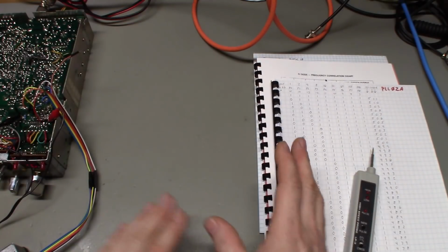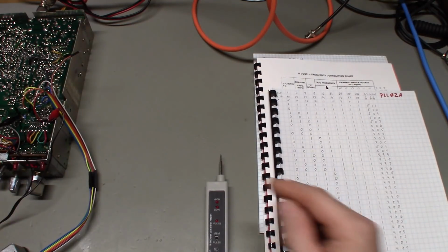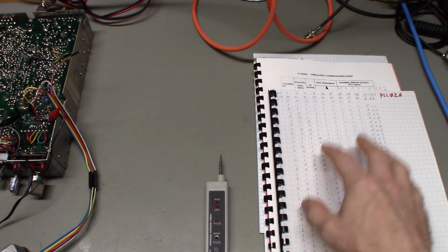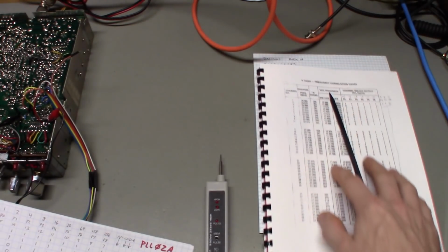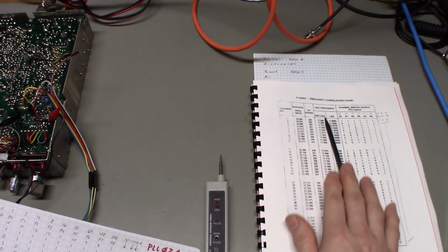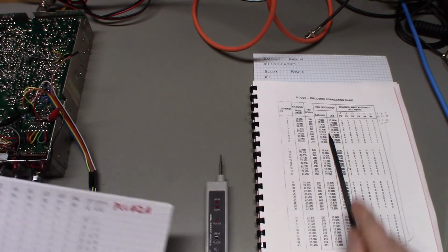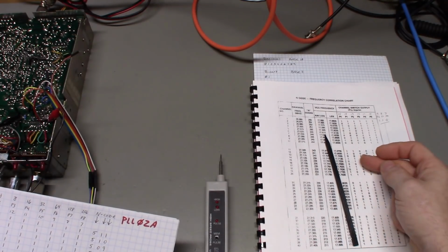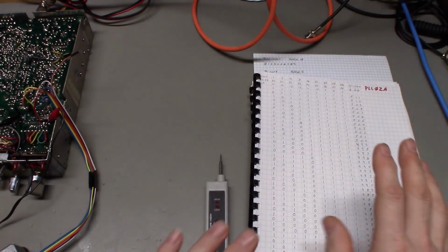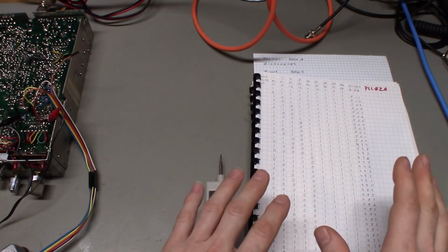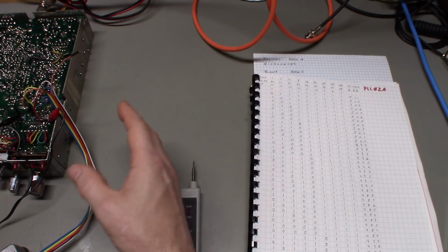So if you did not know what the binary programming is for a radio, you can make your own truth chart. If you don't want to write out a whole book like this, that's fine, but you could make up a chart like this. All you would need to do is find out what the binary code is for one channel. That's it. Because once you have it for one channel, it just counts either up or down from that point. And there's another one of those forwards and backwards things, which I'll get into in a second. It's a unique thing kind of to the PLL02A.